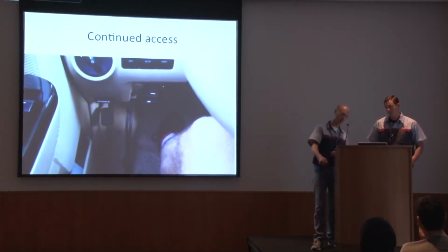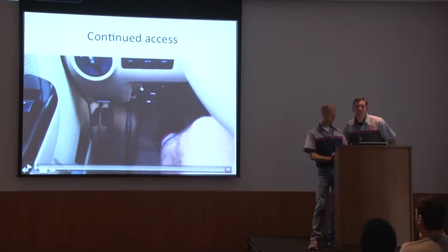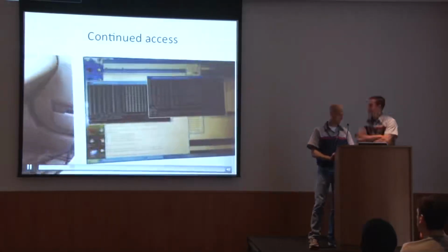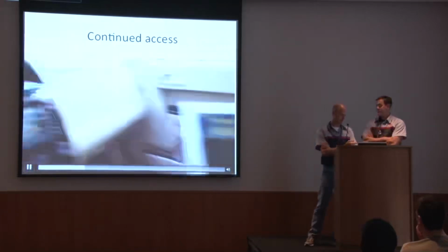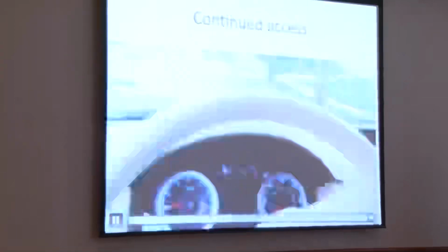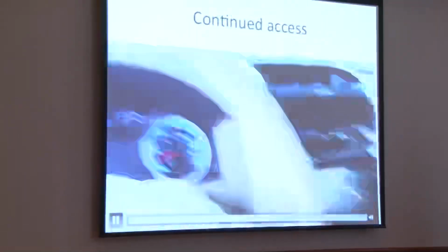I just need to plug into your car for 5 seconds and unplug, and I can still control the things in your car. Yeah, if you're familiar with malware, this is persistence. So I plug into your OBD2 port for a second. I run my program. So there's the program. That's how long I need to be plugged into the OBD2 port. And yet when you're driving along, so I'm driving up, you've got your backup camera on, because my car thinks I'm in reverse.